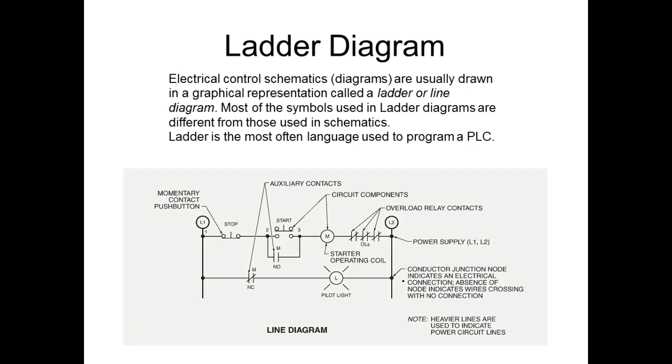Alan, they've moved away from symbols. Now they call them tags. So all our PLC programming languages now are what they call tag based. And what you do is you give a device a name. So that M is not, it's a name. Right? Does that make sense? And what it does is it tells us what contacts are controlled. So I look here, I see this is given the name of M. And down here I've got a normally closed contact that has the name what? M.